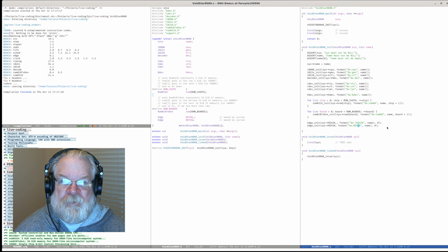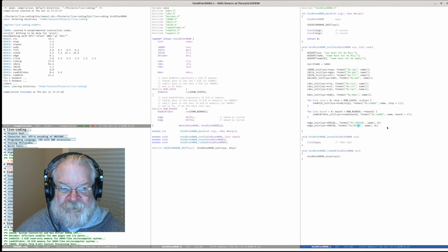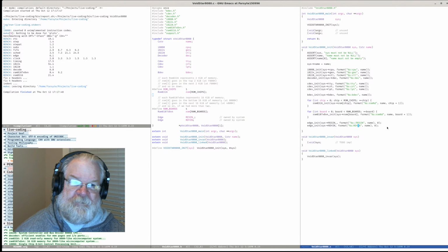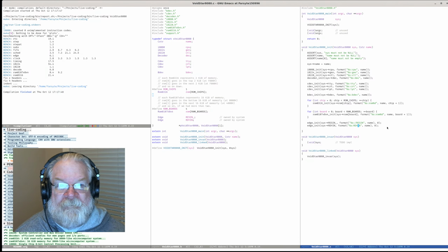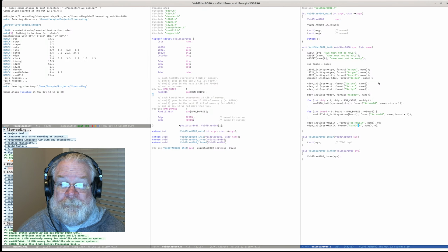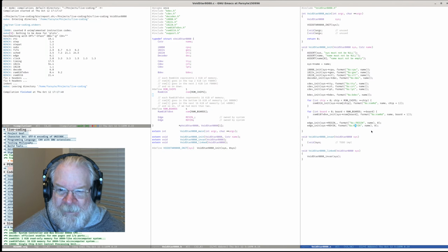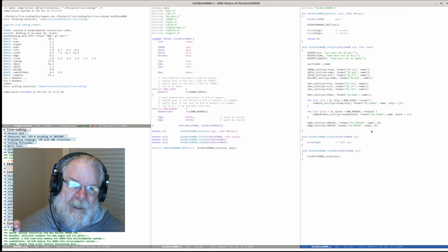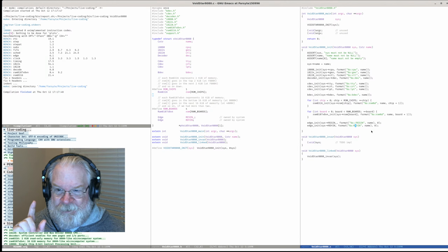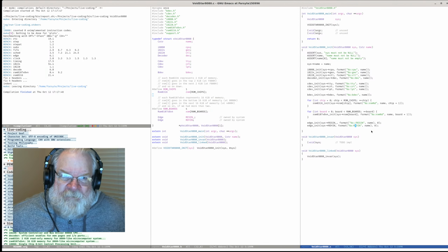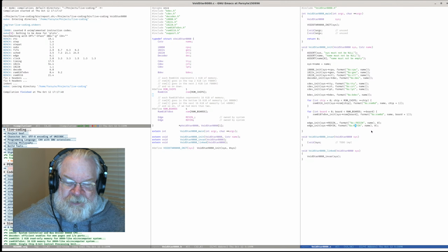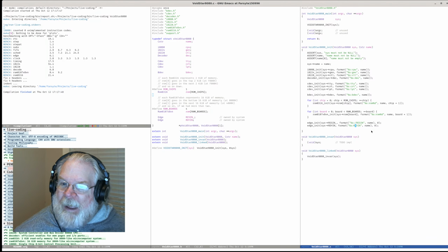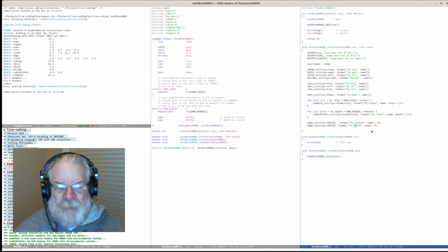If I want to have multiple sources of ready, where CPU sees ready only when all of the sources of ready are saying they're ready, we would have to have some code, possibly in a new module, which would do that. Now, it could very well be that the only place we do that is here, the idea being that only the addressed device would know, but we might have a switch. So we now have two sources of ready. We have the switch on the front panel, which might force unready, and then we have the device. We also have the possibility of, if you make a memory access which doesn't go to a device, maybe ready never comes high. So, thing to bear in mind.